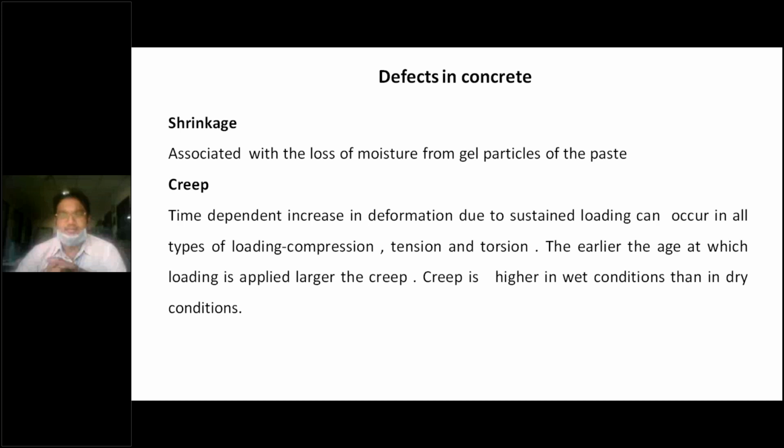This creep is well known even in RCC structures, right? So we always calculate the deflection of any member with its self weight, not with its factored load. In the same way, creep is a time dependent one. It's a long term deflection, which is due to a sustained loading, nothing but a constant loading, which is going to occur in all types of loading: in terms of compression, in terms of tension, and in terms of torsion, right?